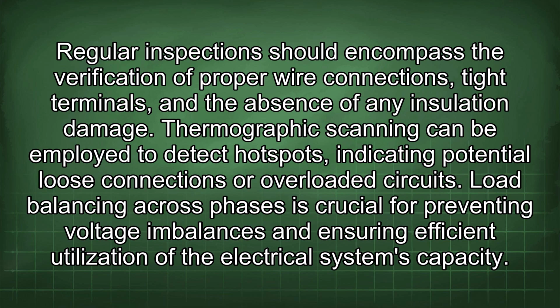Regular inspection should encompass the verification of proper wire connections, tight terminals, and the absence of any insulation damage. Thermographic scanning can be employed to detect hotspots, indicating potential loose connections or overloaded circuits. Load balancing across phases is crucial for preventing voltage imbalances and ensuring efficient utilization of the electrical system's capacity.